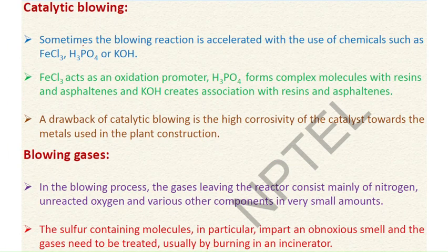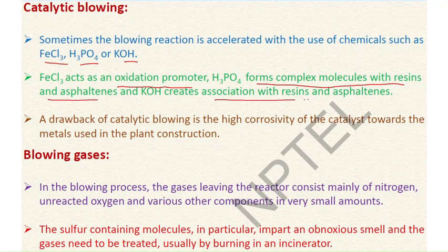Coming to catalytic blowing, sometimes the blowing reaction is accelerated with the use of chemicals such as FeCl3, H3PO4, and KOH. FeCl3 acts as the oxidation promoter, then the H3PO4 forms complex molecules with resins and asphaltenes, and KOH creates association with resins and asphaltenes.